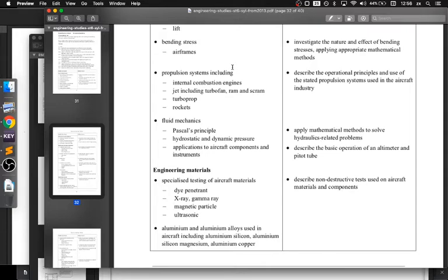Okay, propulsion. I think propulsion's pretty easy. The names are a little bit convoluted now. The thing you have to remember, an example a student told me before, is that the names of these systems get less impressive as they get better. Turboprop sounds more impressive than turbofan, but turbofans are the modern planes that we use the most. Turbojets sound cooler again, and they're the oldest and the least used. I'll talk a little bit about ramjets and scramjets, turboprops and rockets, but we're not as concerned about rockets.